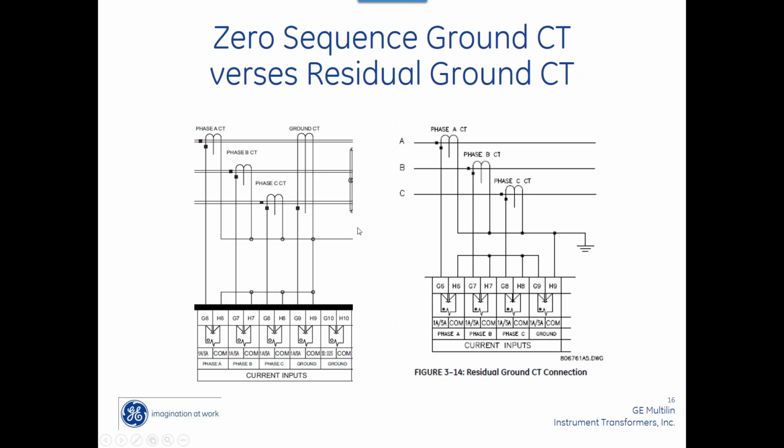Now, one side note, when you're doing protective relays, you'll find that they have a neutral parameter you can set and a 0 current parameter you can set. And what we do is we measure the ground and calculate the neutral, is how it's done in a relay. So even in a protective relay, if I've only got these 3 and I need neutral, I could actually measure it through these 3 CTs and I don't have to go through the residual connection, just for your information.